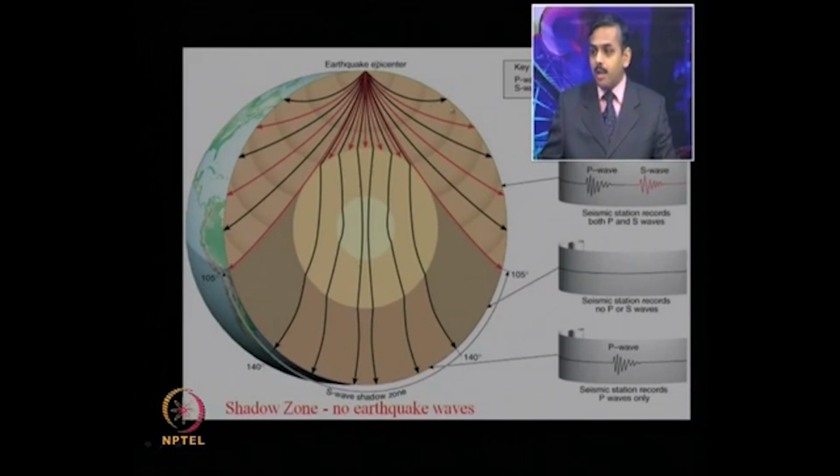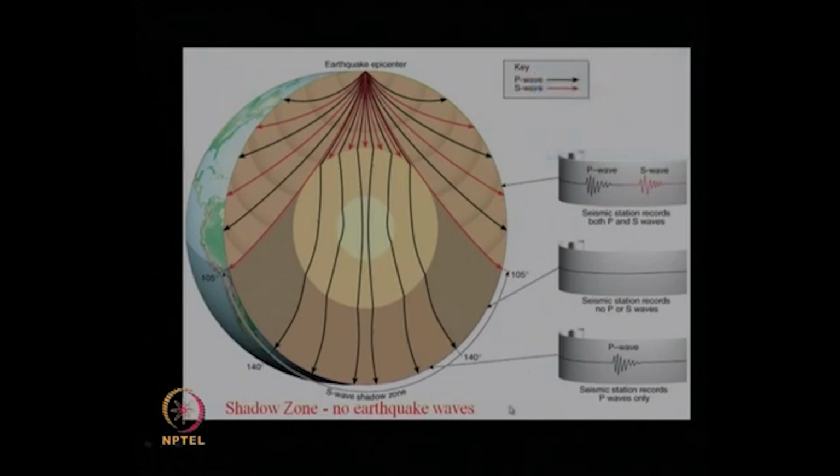So, that way different seismographs located all around the world can record a particular type of earthquake wherever it is occurring, whether it is occurring in a deep ocean or in a desert where human population is not present. Still, the travel of this seismic wave makes us characterize and find out where this earthquake epicenter is occurring. So, we will see how to use this information for the determination of earthquake epicenter.